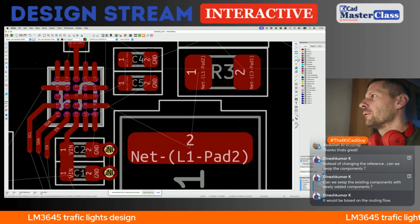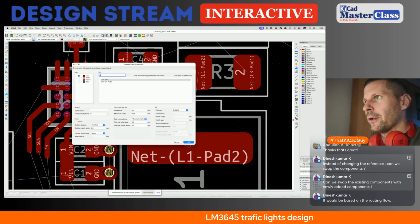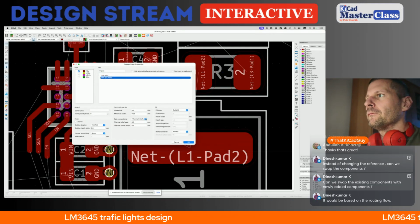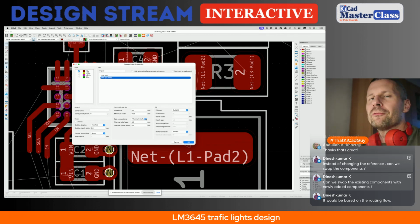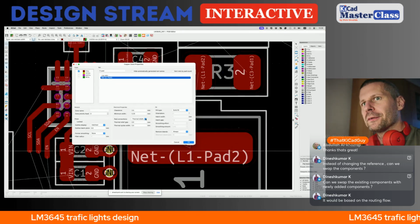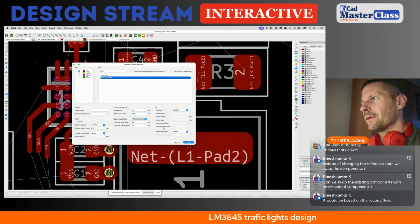Okay, so let's create a polygon for the inductor L1 pad 2. I will keep the default setup because, as you know, when you edit an existing polygon, KiCad will remember the numbers. Otherwise, you have to re-edit them repeatedly.